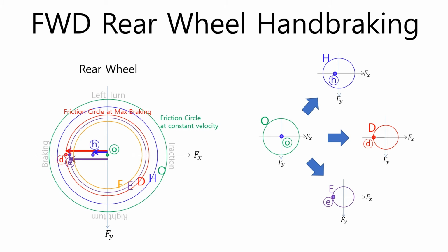If a braking torque that produces a braking force greater than the maximum frictional force is applied, the moment the braking force becomes greater than the frictional force, the absolute value of the slip increases and the friction force decreases.